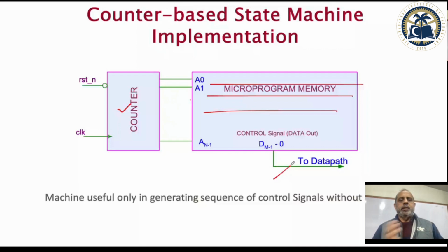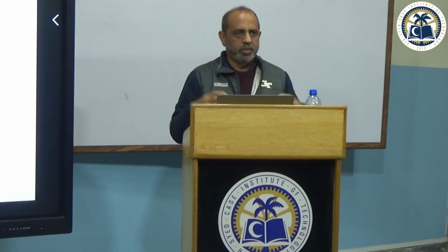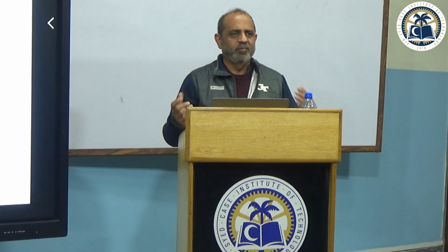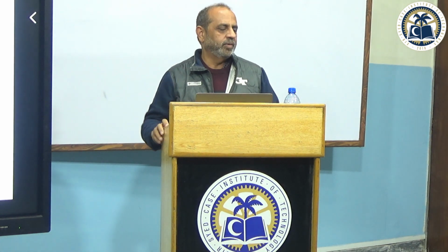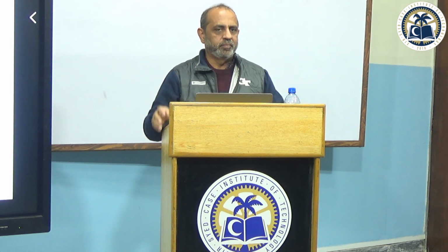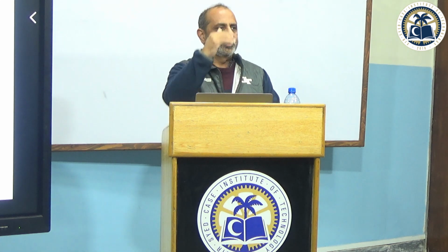So reset will start and it'll end, and you do what you want to do, because in most of the designs the control signals you have to generate run in a sequence always, especially once we are doing time shared architecture. For example, sorting, you are doing a time shared architecture. Whenever I say sort, it is going to generate those control signals in a sequence. Why should I make it very complicated by putting it in a very complex state machine where I know next state is always going to be the next control signal?